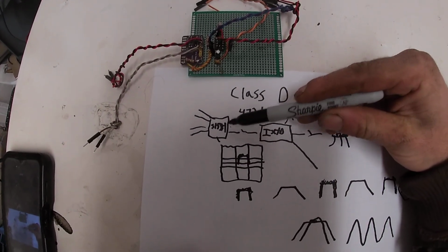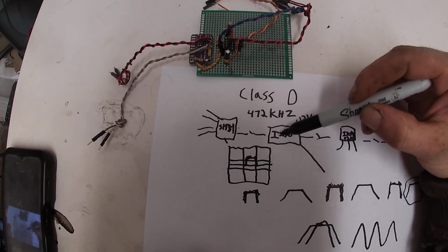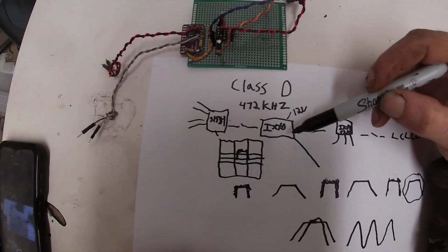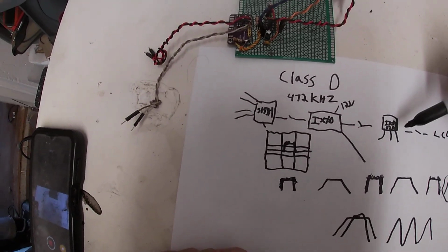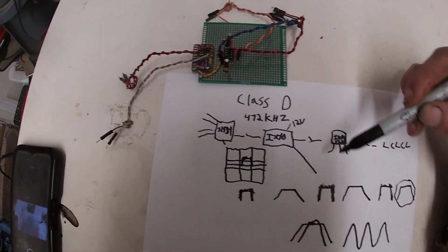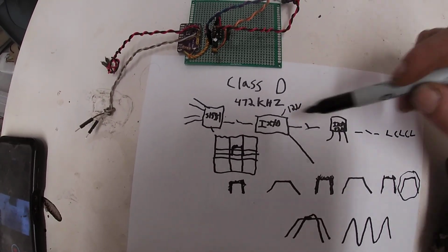Turn power off at a fixed rate using the clock. Use a gate driver to make that switching more decisive, and then put it into a big power transistor. This is very, very efficient because at no point are we trying to make RF. We're not filtering anything in between.